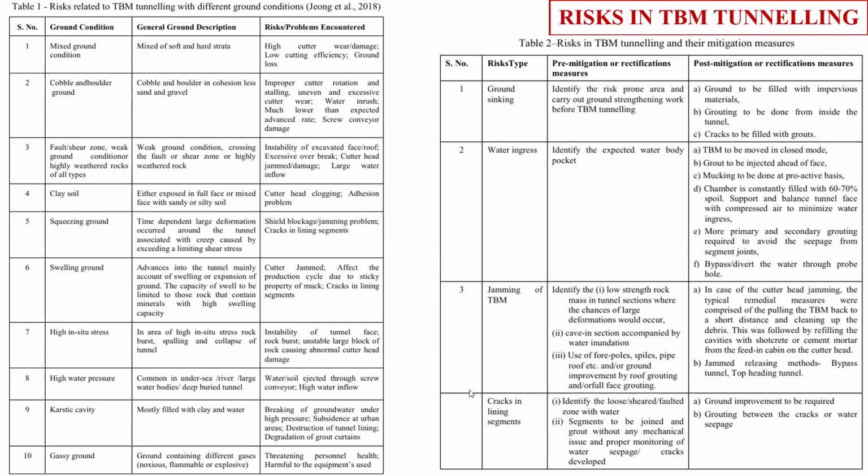But the TBM is a closed mode operation, so you cannot see the TBM face unless it is in intervention mode. When the TBM is stopped, you can go from inside the working chamber to inspect the cutter head. Also, if the TBM encounters a different ground condition, you cannot change the type of supports.